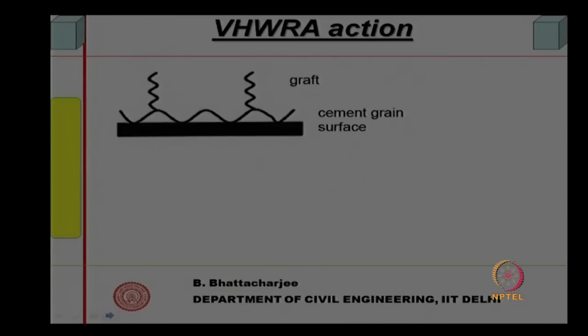So, negative potential has been confirmed by experimental studies through zeta potential studies, and that is what this diagram shows. If you look at very high range water reducing agents or PC based superplasticizer action, you remember we said that this will have a combed structure.